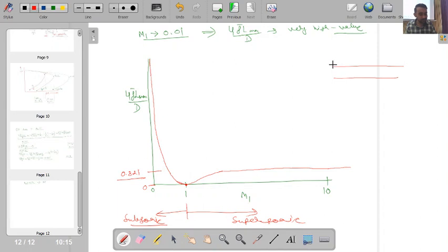So this is a simple physical inference also. If you take a pipe, upstream Mach number is 1, and downstream Mach number is also 1. In this situation we will not have any flow over here. If we are not having the flow, ultimately friction factor will be 0, a static condition. Because ultimately at the length of the pipe, the outstream Mach number we are fixing to 1, and if our upstream Mach number is also 1, it means properties here are the same. So that is the case of a no flow situation, and mathematically I am getting a 0 friction factor over here.